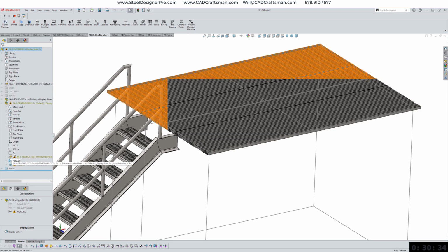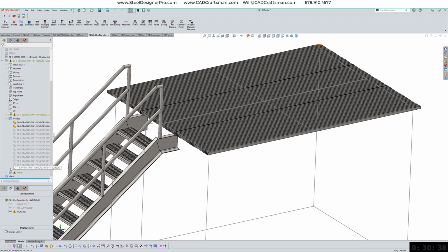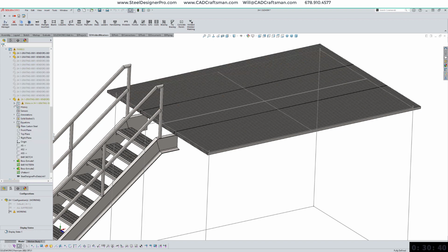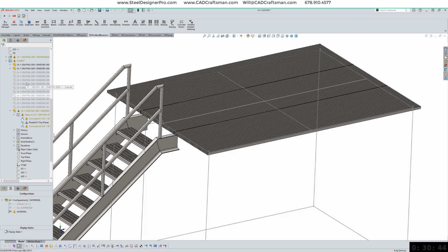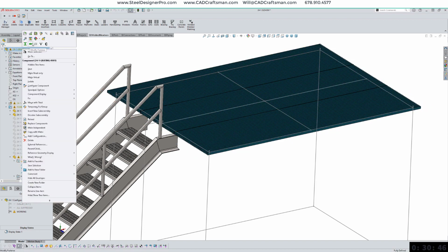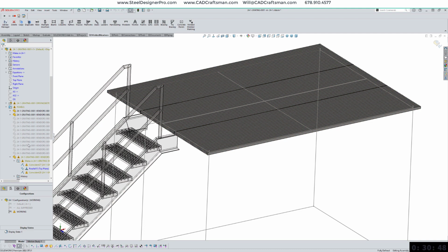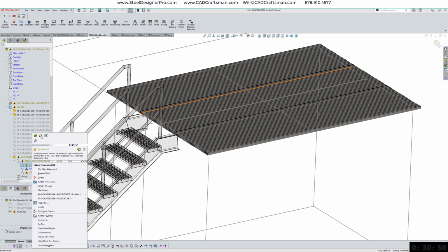With complex member assemblies, SOLIDWORKS sometimes creates errors which may or may not actually exist. It is common with this grate assembly that we have to reset a faulted mate. Suppress and unsuppress is all that is required.